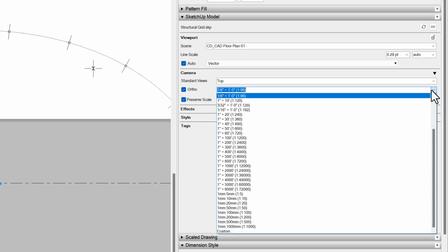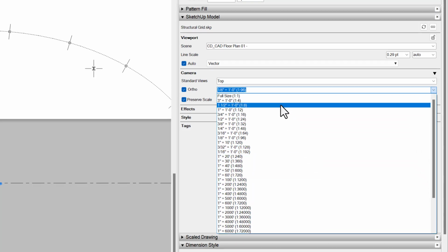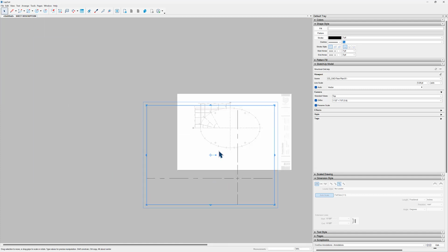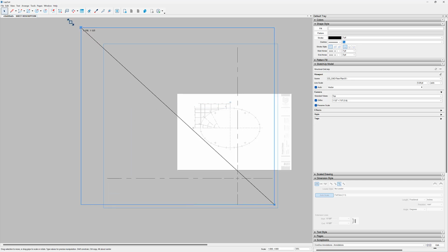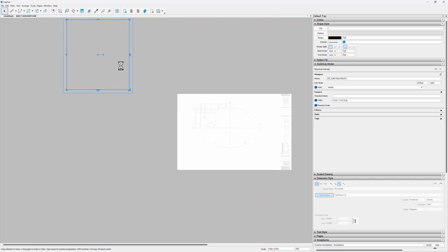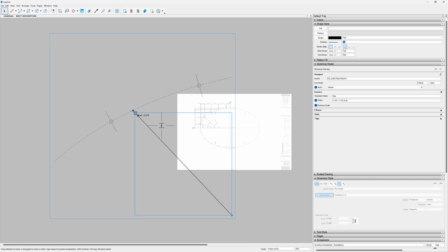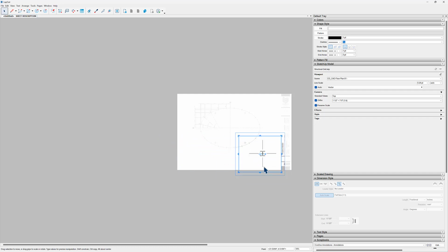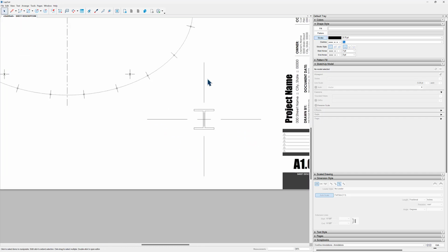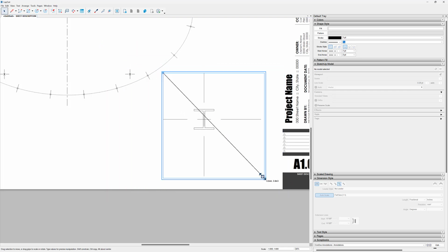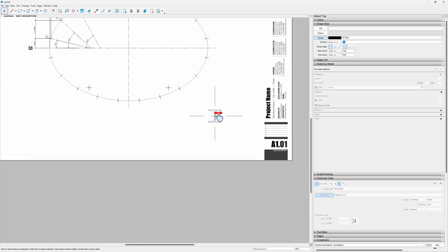We're going to set this to be a much larger scale of 1.5 inches equals a foot. And I'll just stretch this out like that, kind of zoom way out, stretch this around. And I'm just looking for that column. I know it exists. So we're gonna scoot it down like this. There it goes. All right, so there's my column. So this is how you can create details. These are like that. And I would say that maybe I don't need as many of those column or those grid lines to be represented like that.